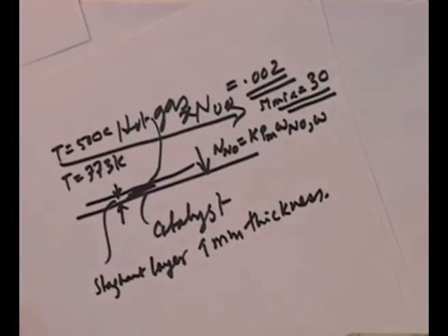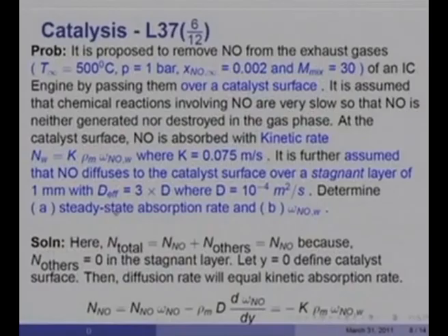All right. So, that is what we will do, and you have been told that in this very small layer, remember, there will be some effects of turbulence, and therefore, although very small, we are told to take D effective equal to 3 times D, the laminar diffusivity, and the laminar diffusivity itself is given as 10⁻⁴ meter square per second.